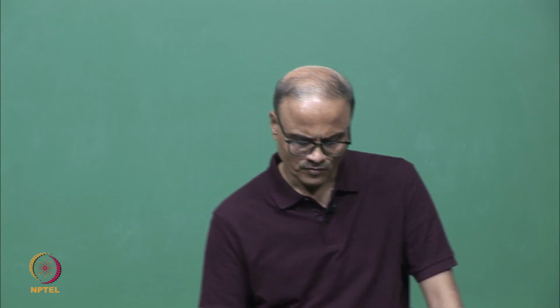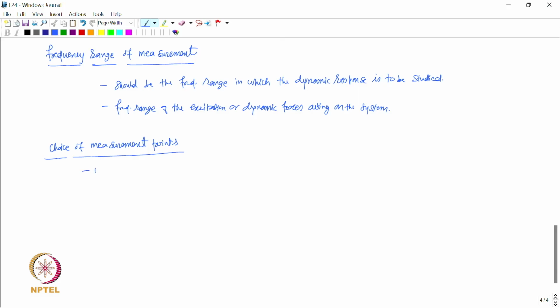Okay. So, if the objective is to have an estimate of natural frequencies omega n's and damping factors of the modes. So, this can be done using measurement of few FRFs, right, can be done using few measured FRFs.